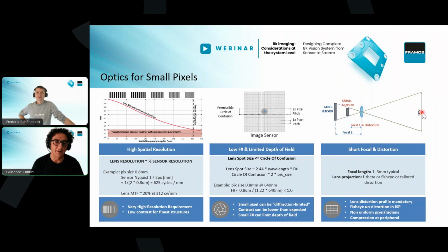There are some lenses that could be closer to that, in special M12 lens, or there are variants of the sensor that come with smaller CRA in the range of 10 degrees. And in this case, you have a very good chance to find a lens, M12 for example, with the matched CRA.